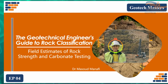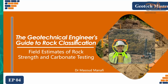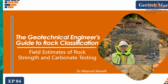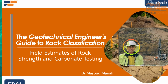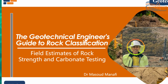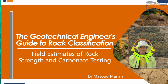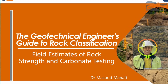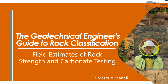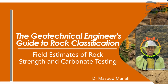We'll learn how to estimate the unconfined compressive strength or UCS using nothing but our hands, a pocket knife, and the geological hammer. We'll also look at chemical testing. We will learn how to use dilute acid to determine the carbonate content of a rock. These are simple tests, but they provide critical data for our engineering modules.